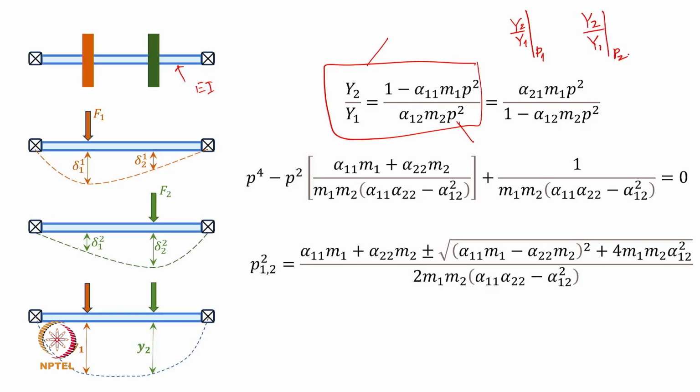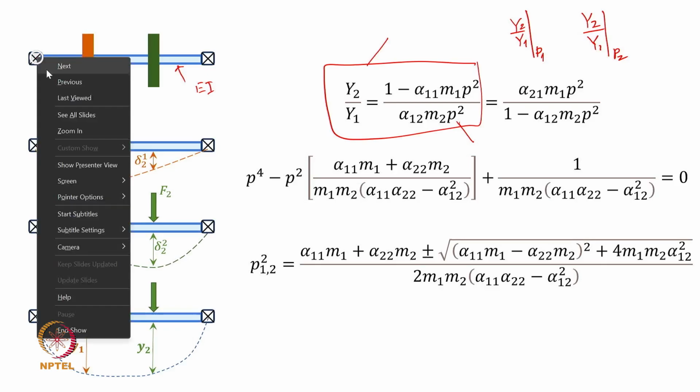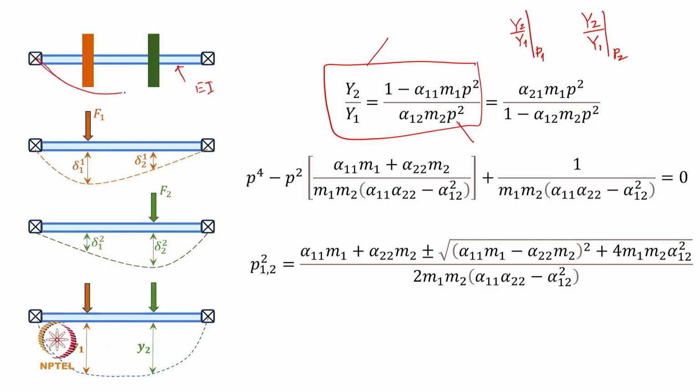Okay. And with that you get an appropriate mode shape, and although you can find this out by appropriate numeric values, it so turns out that the first mode will show the mode shape to be this, which is expected, right. So, both the discs are going to move in the same direction, whereas in the second mode this disc can have this peak value and this disc will have this peak value, and so on.